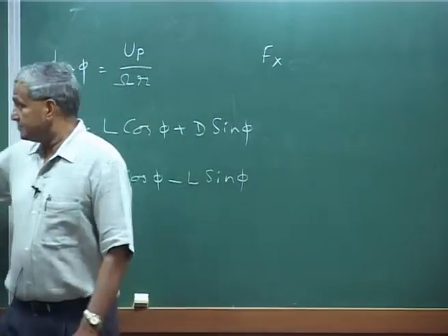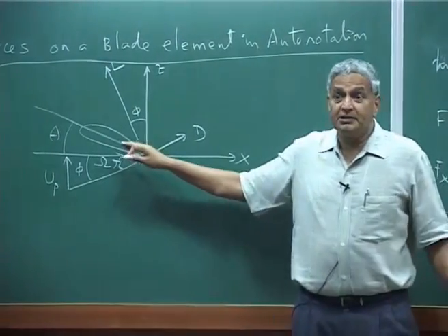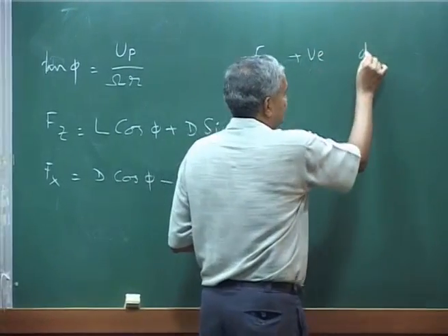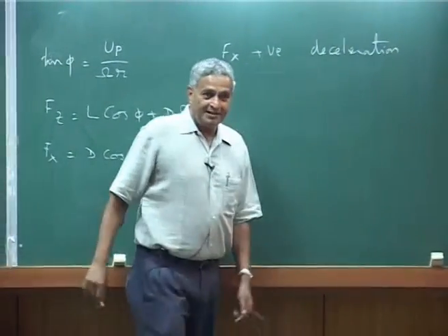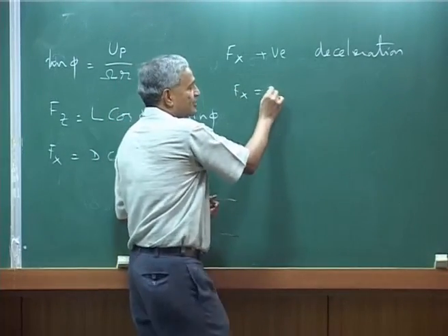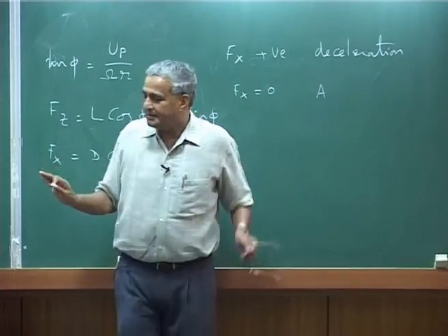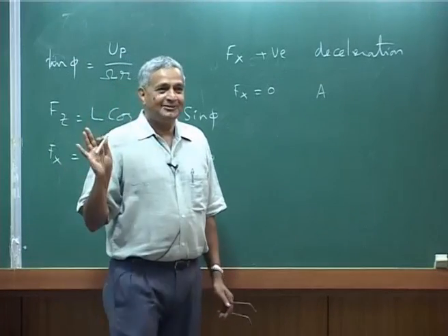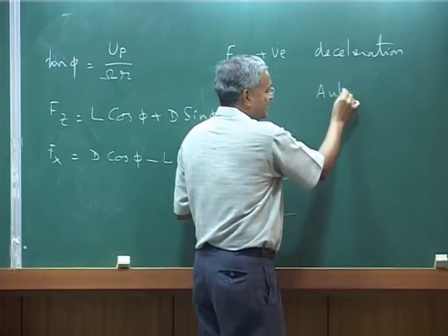your rotor will, because no other force, only Fx is acting, it will decelerate, okay, because Fx positive means deceleration of the section. If Fx is 0, that is auto rotation basically, because there is no force acting, it will continue to rotate with that omega r. This is the condition for auto rotation.